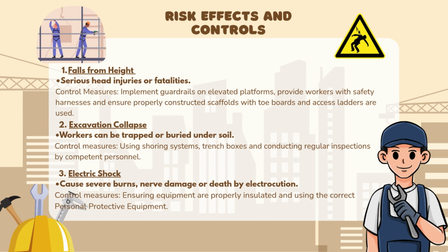Electric shock can cause severe burns, nerve damage, or death by electrocution. The key controls here are following lockout procedure, ensuring equipment is properly insulated, and using the correct personal protective equipment, such as rubber gloves rated for high voltage work.